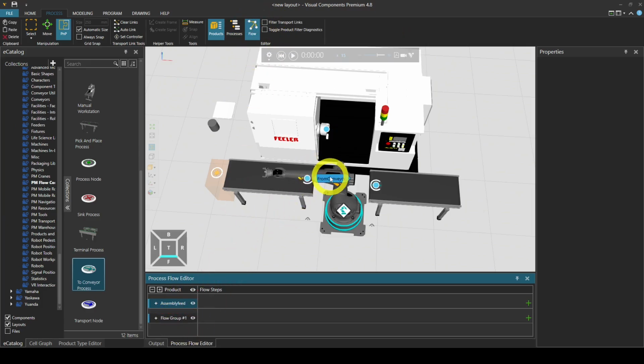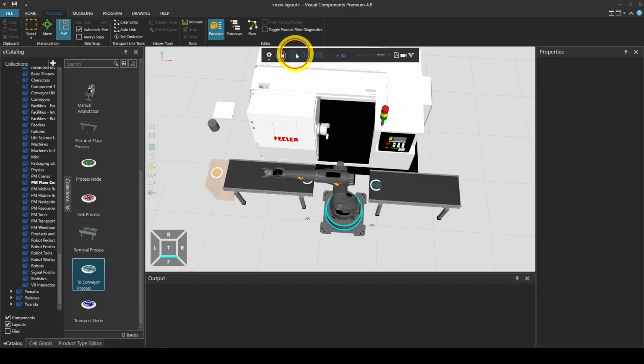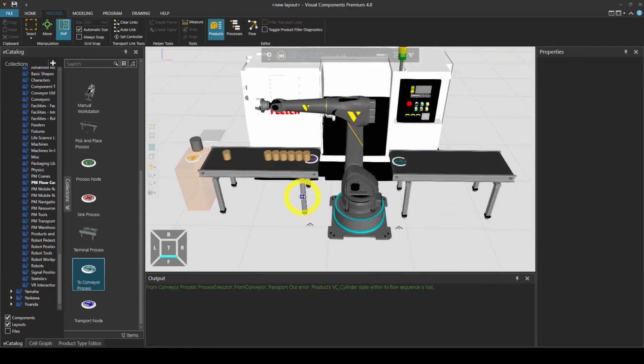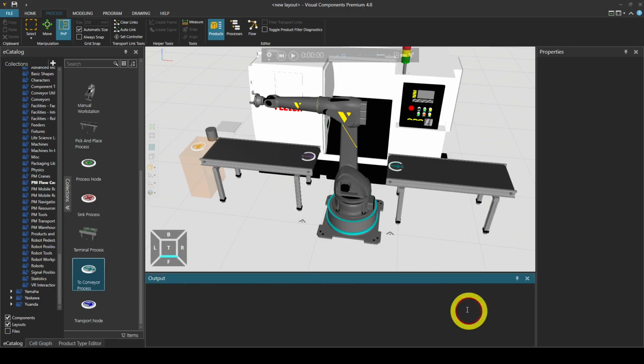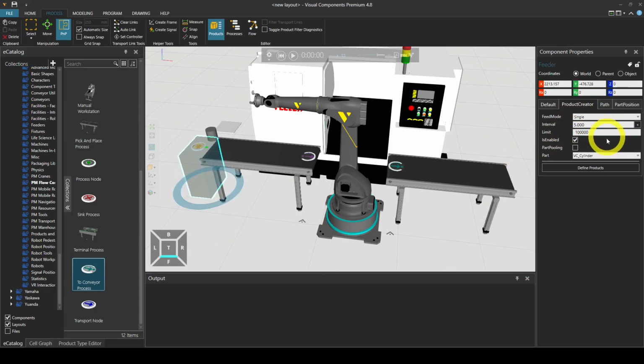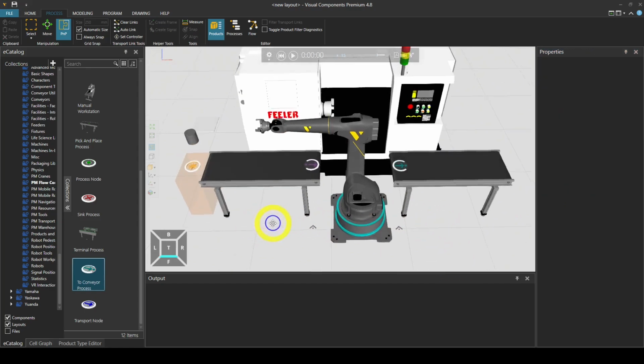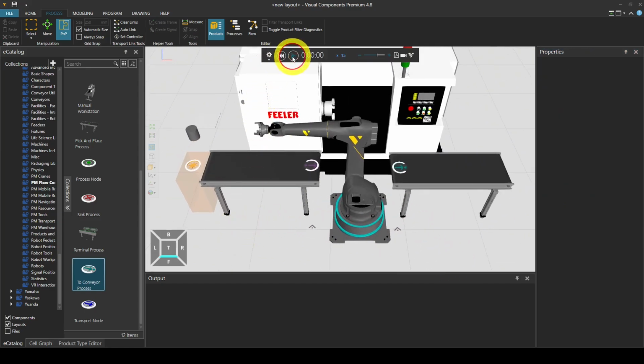So once all these works are over, the next important step we are going to create is the processes. So we'll go for the flow. So under the first process, what we have named is assembly feed. So first link has been established and second link has been established. So now we'll feed it up. And you can see it is regular component. And now we'll change the feeder property. So reset, select the feeder, product creator, change it to raw material, that is the assembly what we made.